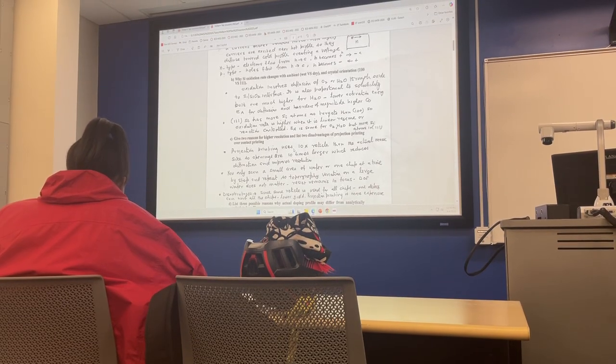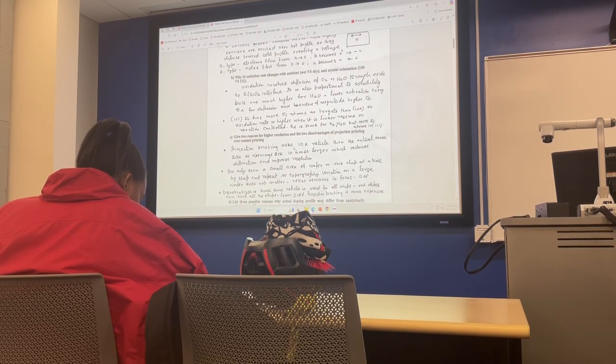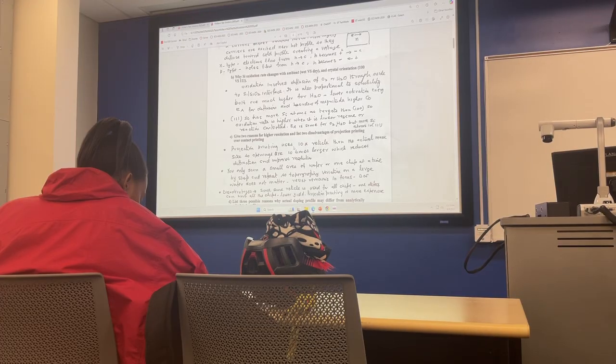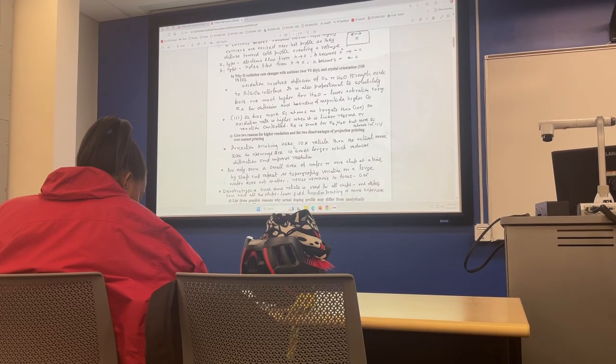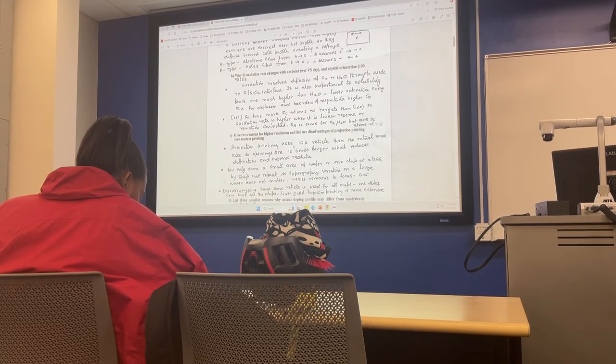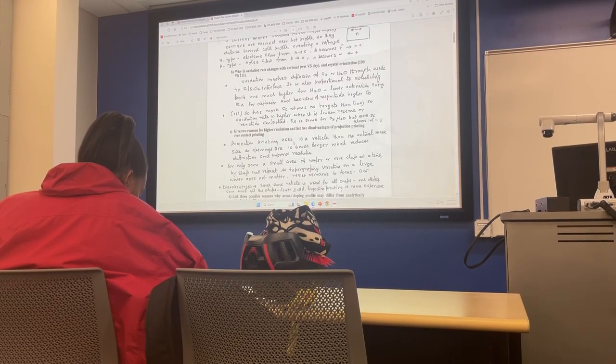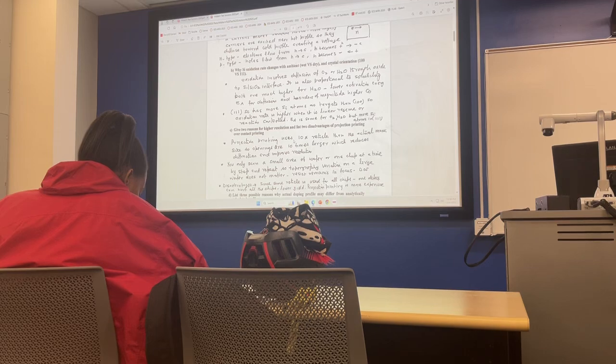Your depth of focus would have to be very large if you exposed the whole wafer, and the whole wafer can have a much bigger variation in roughness because it's a large area. But if you do only a tiny area, chances are the topology variation is not that great.